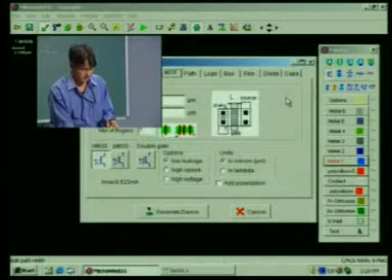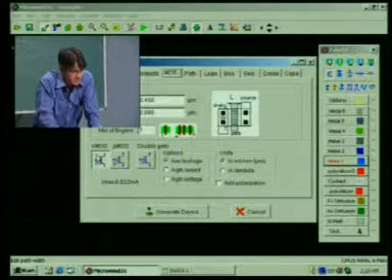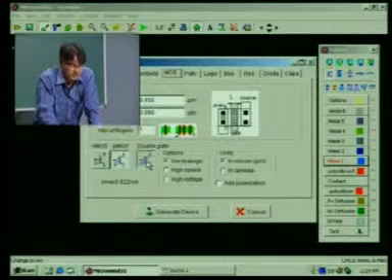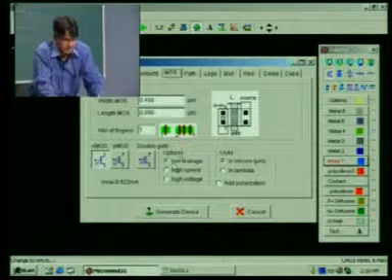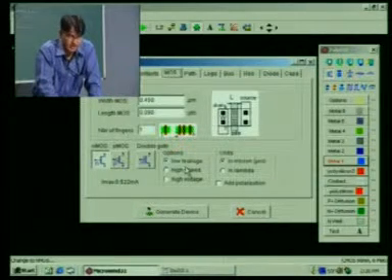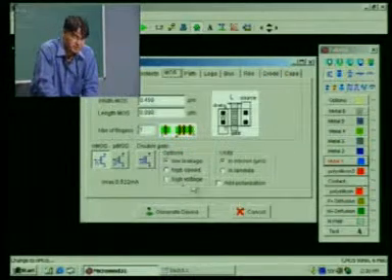But for a big design we can't go like this. This comes under semi custom design. I am creating a basic MOS, then a basic capacitor, a basic resistor, which is not possible for a big design. So I need some full custom kind of designing. There is one MOS generator: you just have to select N type, P type, or double gate. Suppose I select N type, what kind of basic MOS you need, according to specification, like low leakage, high speed, high voltage. Just generate it and put it here.